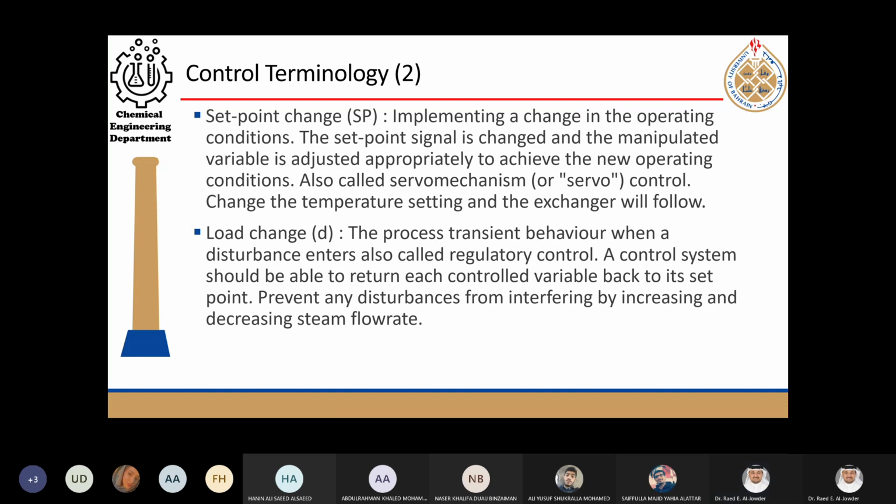So what do you do? Well, I fix it and I try to protect it. So the second concept, which is the load change or the disturbance rejection, has been born. And what does this concept do? You say, okay, I want 100 degrees Celsius. What are the disturbances? Disturbances is flow rate. Okay, please protect my system against flow rate changes. So you are monitoring flow rate changes and you are adjusting the system accordingly in order to protect your system. So those are two different concepts.